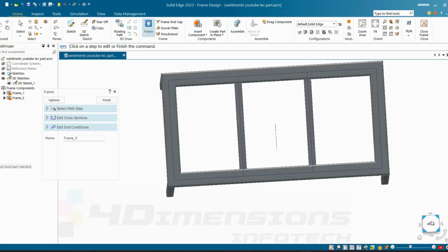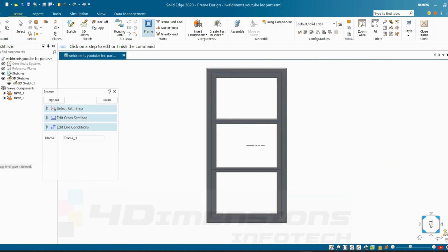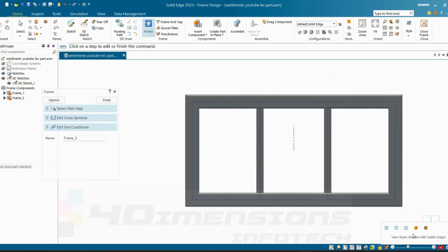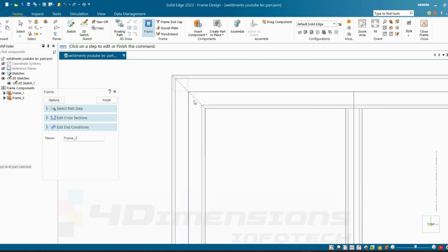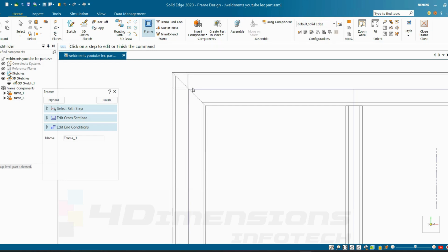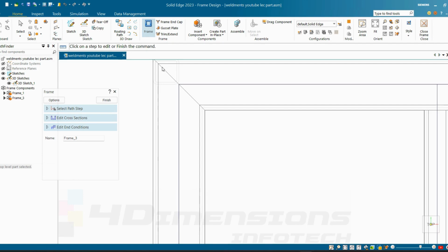But if we observe from the top side, I'll orient it a little bit and I'll make this part transparent. These square tubings are not coming at the corner point of the sketch. Earlier rectangular sketch, this corner point you can see here. These tubings are not mounted according to the reference of this point. They are at the extreme corners. So I want them to be placed at these mid corners here.